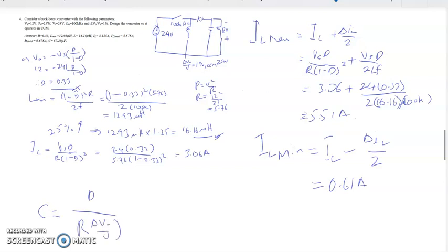So in terms of C, it's mentioned over here, the delta V naught, V out over V, the difference or the range of our output voltage. This one is current regulation, this one is voltage regulation, should be within 1%. So delta V naught, V out over V average is 1%.